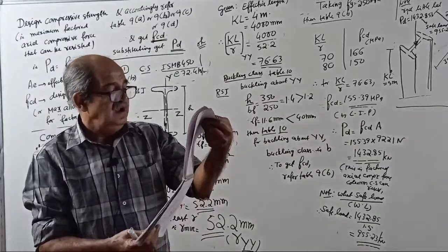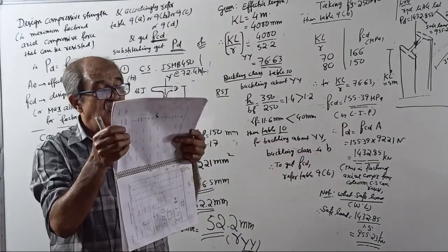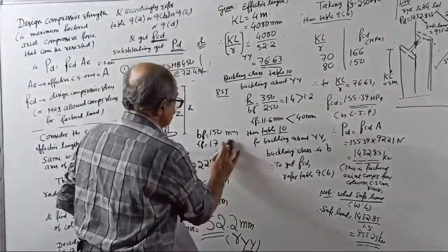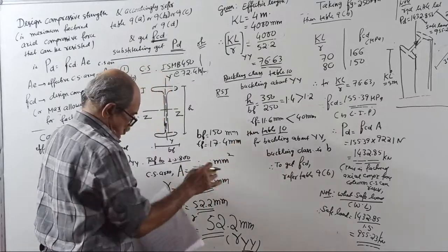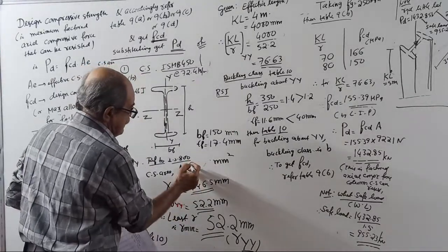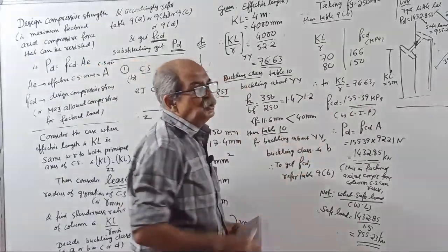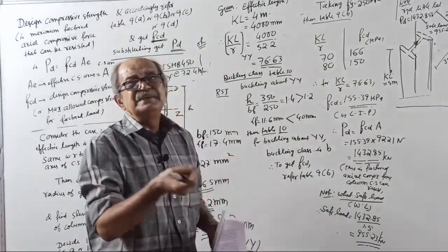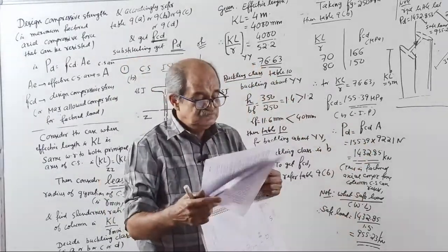Now I have to search here, ISMB 450. Thickness of flange is, still you have not told. Okay. 17.4 millimeter. And its area is 9227. Same as last time. But someone will say, sir, last time it was 9221. That is because of approximation. Because of the curvature, all slight changes. Okay, 9227, last time 9221, both are the same.